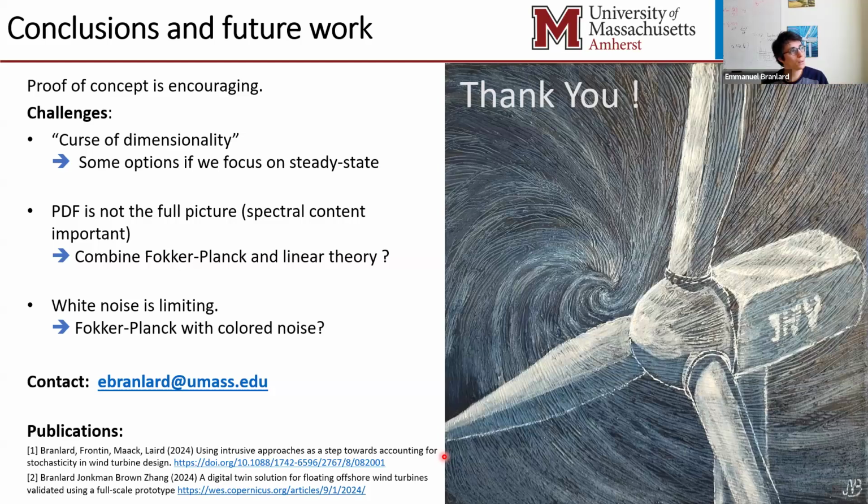No, I haven't, and I think that's a very fair point. You could expect way more displacement, way more nonlinearities showing up for those events. And you're right, if you care about tails of the distribution, you might get into trouble. So my way around this, right now, is I'm trying to minimize the simulations when you are at operating conditions where for a given wind speed we have some nonlinearities, but you can probably get 90% of the results out with a linear model. That's my take. But you're 100% right that for extreme events, this is where this approach won't work.